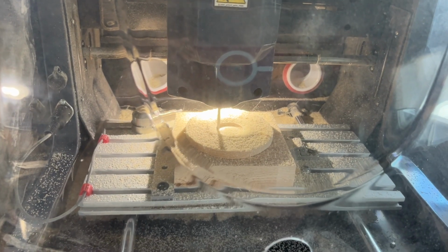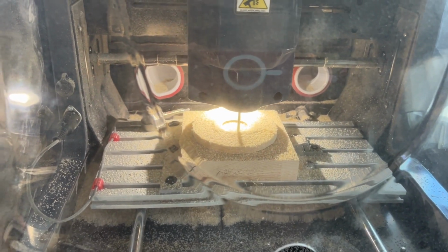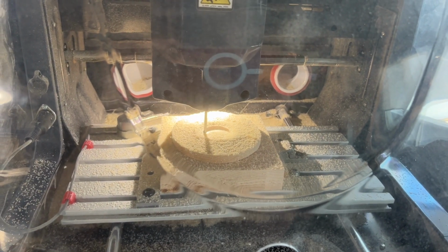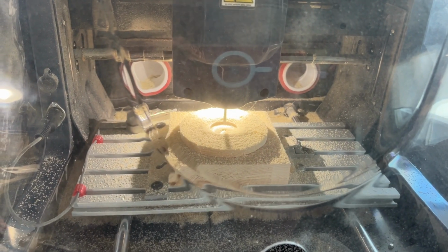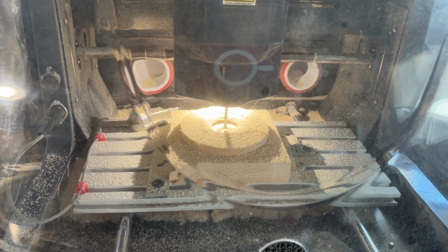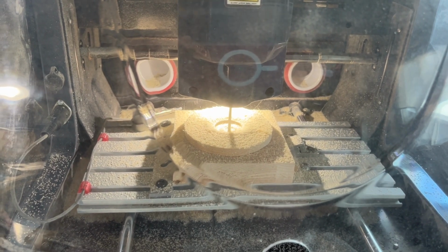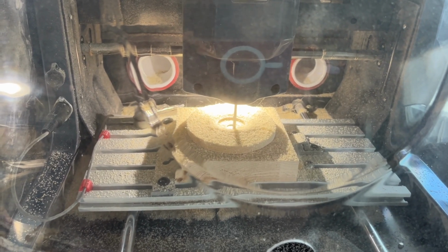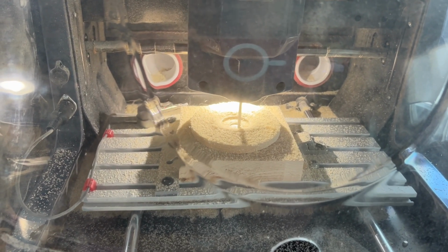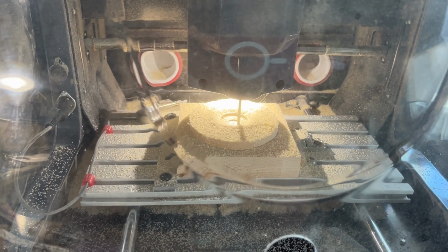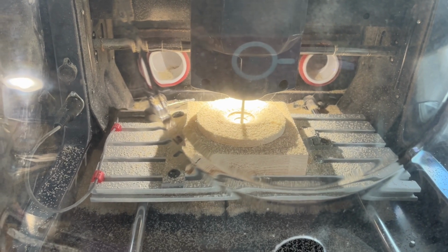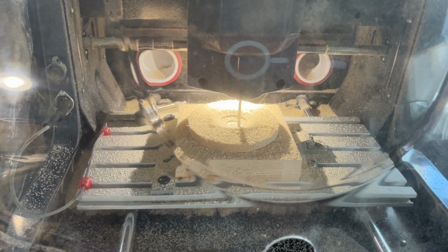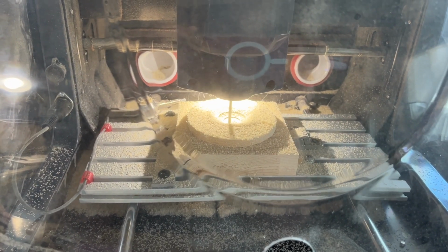All right, now there's a couple of things I forgot to show. I still had tool number 3 in there, and I did the outer ring for the insert. It's only down 0.8 millimeters in terms of overall depth, if I remember correctly. We'll go back and look at that. I did swap out to tool 10, which is a 2 flute, and it happens to be a long one. So I did chuck it up all the way to where the shoulder is in the collet. And now I'm running it because this is going to go 25 millimeters deep.